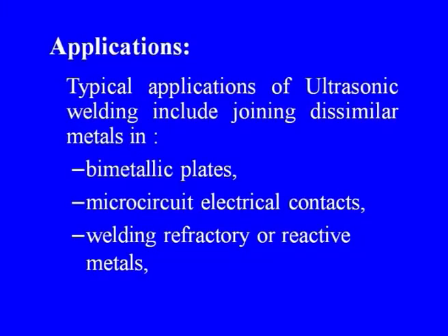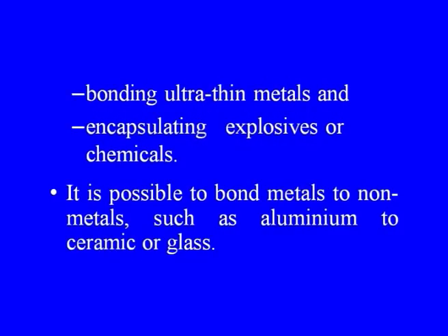Applications of this process include welding of bimetallic plates, welding of microcircuit electrical contacts, welding of refractory or reactive metals, bonding of ultra thin metals, and encapsulating explosives or chemicals. It is also possible to bond metals to non-metals such as aluminum to ceramic or glasses.